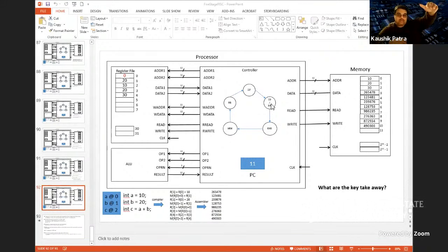So your implementation becomes: depending on the state, if my state is this, and if my instruction or instruction group is this, do this action. It is just repetition of that type of coding. If my state is instruction fetch, do this. If my state is instruction decode and ID/RF, and you have already parsed it, then if it is an R-type instruction, access the register file with the corresponding operand register values from the machine code and read them, issue the read signal to the register file, etc.